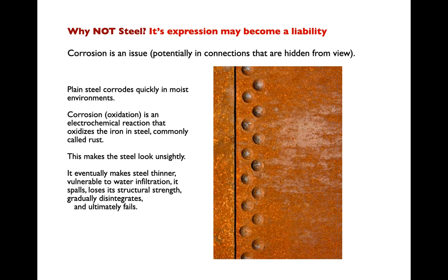And when we expose steel to outdoor air, like I said, we worry about corrosion. We all know that steel rusts. One of the problems with this is that oxidation not only kind of chews away at the steel section, so over time there's less and less material there, but as we talked about when we were talking about rebar, oxidation also makes the steel kind of blister, right, and puff up. And this can put an incredible force onto connections that we maybe had not anticipated. It's also unsightly. We don't like to see rusted steel.